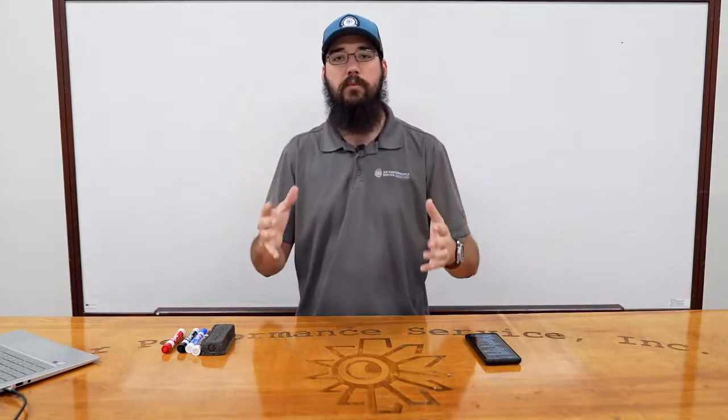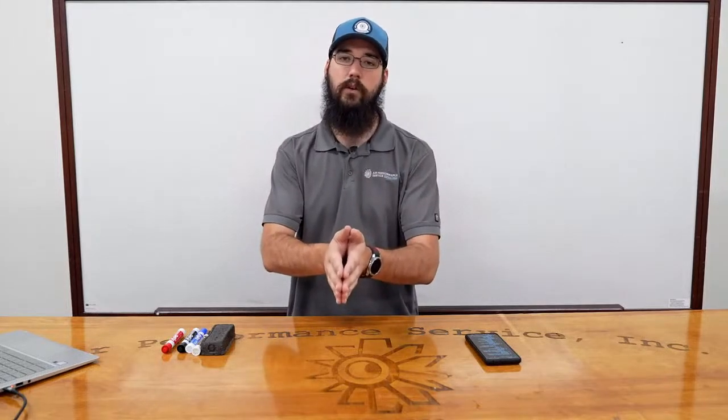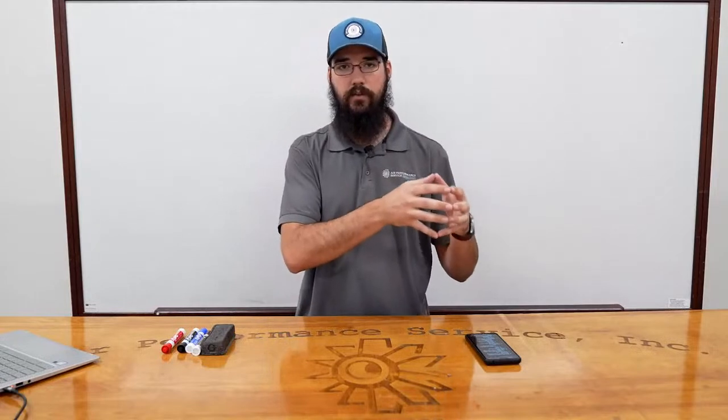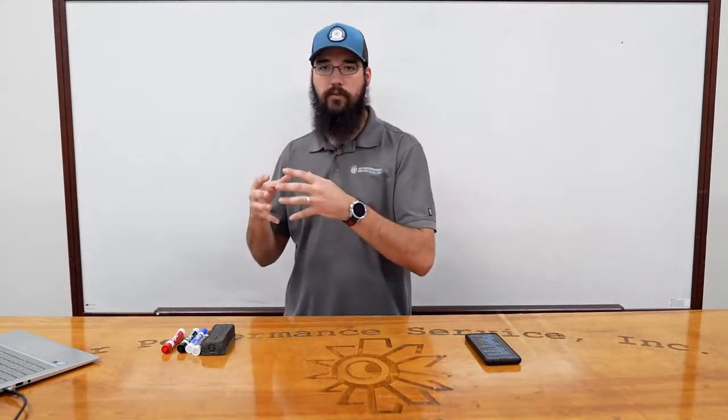That we can identify the fact that, okay, we know from a procedural standpoint, we're just not moving enough air. What it really means is we're not putting enough heat into the coil. So that is where the air side of our system really starts to integrate and become so vital to the overall function of the refrigerant side.